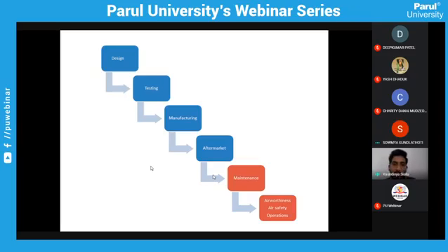Then you will know the Brayton cycle and the basics of the theoretical part. So that probe after the propulsion, which we used to call EGT, exhaust gas temperature. We measure that, and depending on the various values and combinations of values, we will be determining if the engine is working in good condition or not. It's a big chapter. If we have time later, I will discuss that in another session. So let's go back to maintenance.